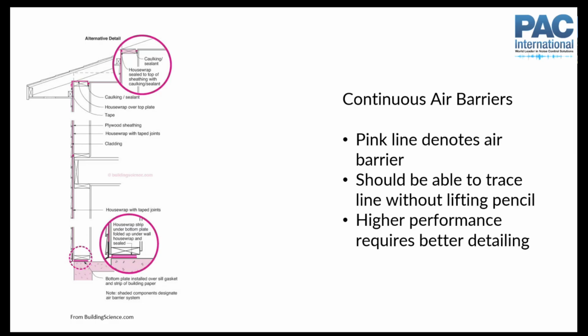And when you're thinking about an air barrier for your building envelope, you're trying to reduce the number of air changes per hour, these kinds of things. It's not enough to simply specify and select some air barrier material and say, hey, put this up and you're done. No, you have to pay attention to all of these little details. Anytime there's a penetration for something like a hose bib, or you have discontinuities where you transition from your wall to your roof or your wall down at your base plate, all of these little gaps and corners and cracks and crevices you have to pay attention to and figure out how to address. Same sort of thing for acoustics.